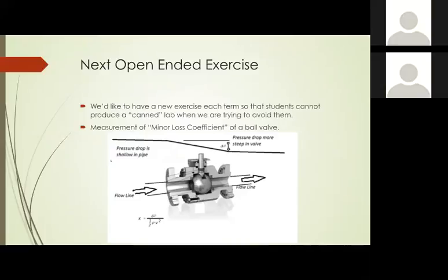We're going to see that minor is a relative term here in a second. So in this diagram, I've got fluid flowing into what's known as a ball valve here, and if you measure the pressure along the line, you would notice that the pressure declines rather slowly along the line, and it's caused by fluid friction. Suddenly you get into this strange thing that changes the way the line looks.